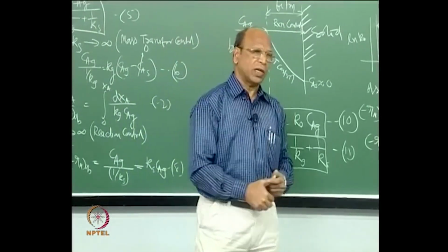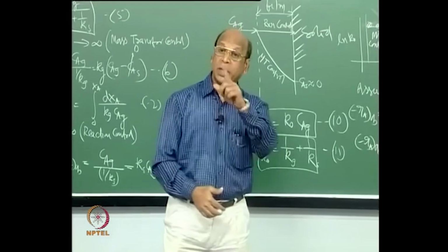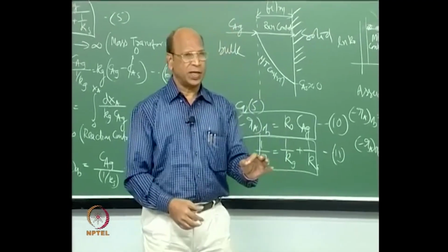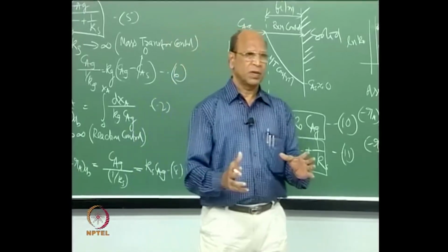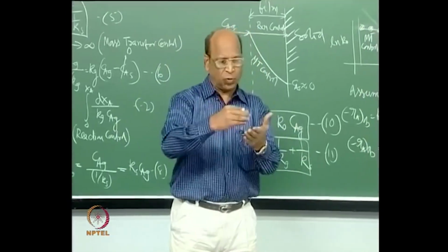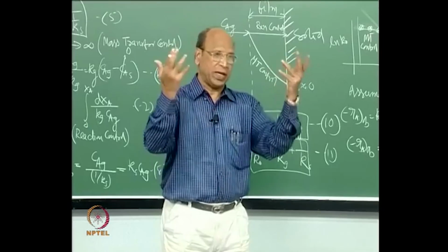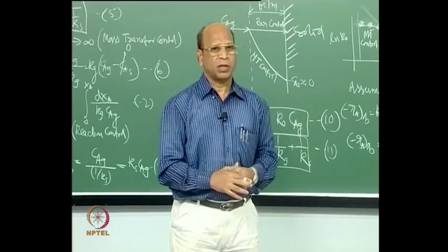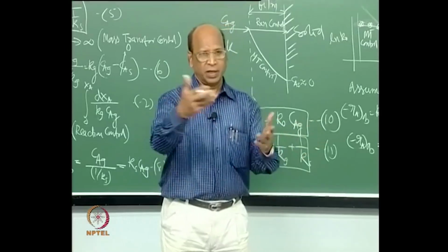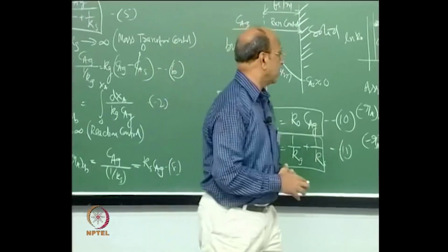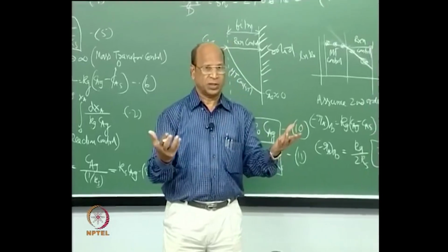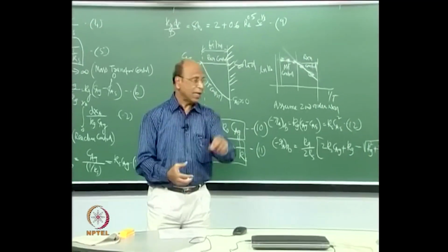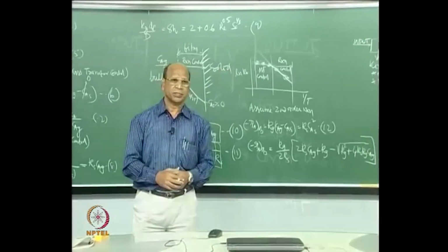The second thumb rule I also told you is temperature control. Highly exothermic reactions, even if gas phase, can be very sensitive. That means a 1 degree change this way or that way, we may catch fire. That fire we definitely have to avoid, otherwise the persons working in the industry will not be there, because of explosions. So under those conditions we can again go for a mixed system.